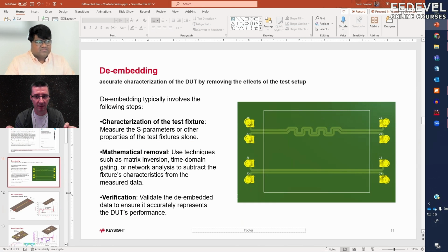And what we can do in the oscilloscope is take the S2P parameter models of this interposer and do this de-embedding, and mathematically we can actually see the signals which would be measured directly on the pins of the memory, even though we are not measuring directly on the pins of the memory, we are measuring on the interposer. Correct? That's okay. Yeah.